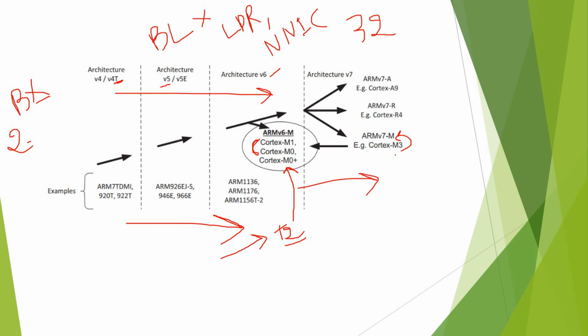Moving to ARMv7M. ARMv7M included all the extensions and features that had been added on ARMv6M, and even extended the existing blocks and features. So by default now, the execution state of the CPU for any instruction, whether it is 16 or 32-bit, will always be T2. We have now a rich instruction set. In ARMv6M, there was more focus on the 16-bit instruction. Now we have both capabilities to boost the performance.